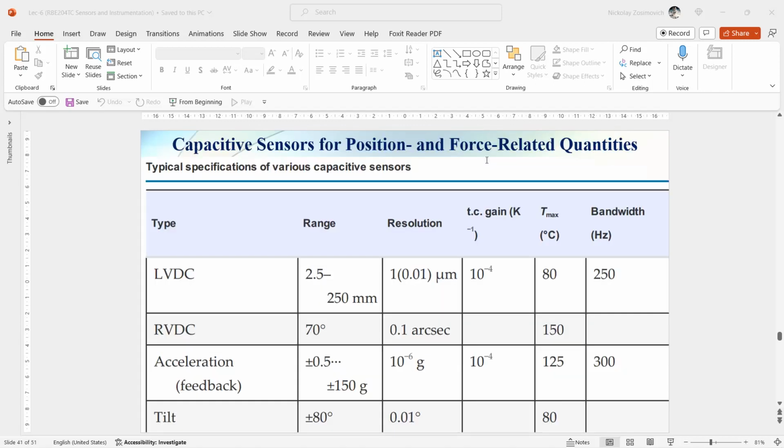As with all displacement sensors, capacitive displacement sensors can be modified to make them suitable for the measurement of angular rate, acceleration, force, torque, mass, and pressure. Differential configurations are recommended and, where appropriate, a feedback principle as well, to reduce intrinsic sensor error.